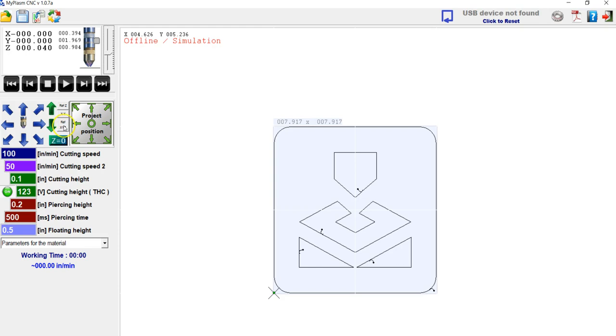We also have the reference home for x, y, and z. This will set the total table 0. This will also allow us to have something called soft limits, which is also present in the program. It's a redundancy. It makes sure that we don't end up running the table into itself along some other part of the table. So just keep that in mind, reference X, Y, and Z. And then we have a reference X, Y, that's just homing the X and Y. And then lastly, we have referencing of the Z. And that is the basics of the control.